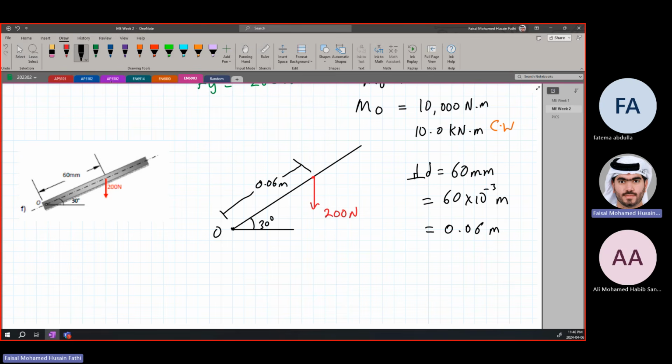Again, we will solve it the exact same way. If we connect this triangle, this is a right angle triangle. So if this is 30, this one is going to be 60, and this angle is going to be 60. Before that, let me just draw the components. We're going to need a perpendicular component and a parallel component, I should say. So let's call this Fx and let's call this Fy. And this is our 60 degrees right over here.